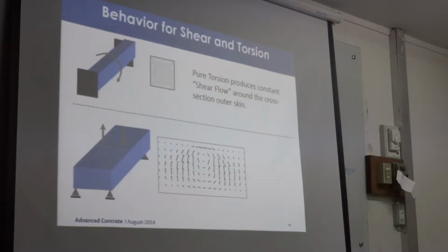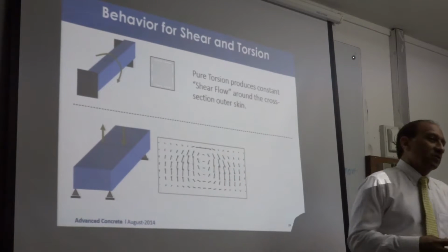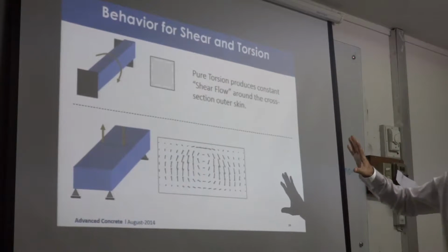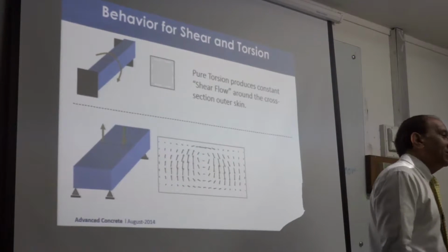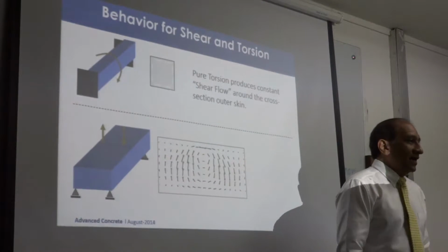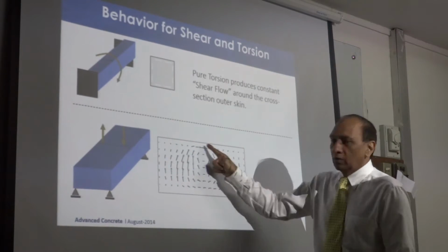When they did the actual design, it came out to be 125 kilograms per cubic meter, which means a lot of extra money, which they don't have because they already got the project. Now they got worried, what is the problem? Why is it costing so much? So the project came to us a long time ago before they started the construction. This is in fact one of the first projects we did on this, trying to figure out why it is costing so much. And you know what we found, interestingly, that the pile cap had a torsion, and they were putting the combined shear and torsion reinforcement to go around.